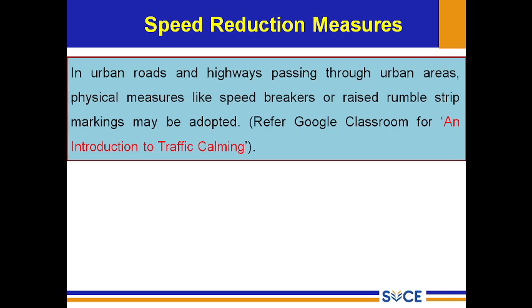However, the case in India is quite different given the heterogeneity and the multiple modes we use on roads. The velocities of different vehicles vary, and based on the road condition, whether urban road, national highway or state highway, the operating characteristics are widely different. Vehicles vary from tractors to animal carts, all sharing the common carriageway. Highways passing through villages and towns are also shared with local traffic, resulting in wide variation in direction, speed, and vehicle mass.